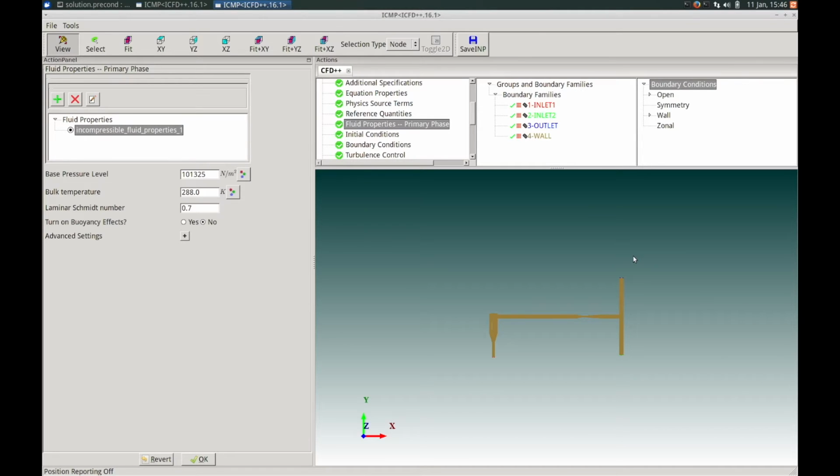Two different solution algorithms are available for the solution of incompressible flows. These two algorithms are referred to as the preconditioning algorithm and the fully coupled pressure-based algorithm. The use of both algorithms will be illustrated in this example tutorial. In addition, the tutorial will also demonstrate the use of a passive scalar, also known as a color tracer, to mark one of the incoming streams so as to visualize the mixing of the streams within the T-junction.